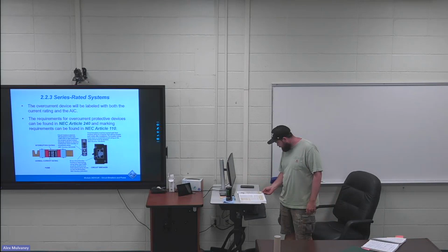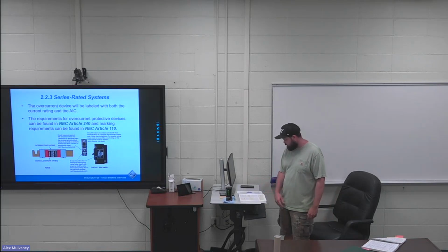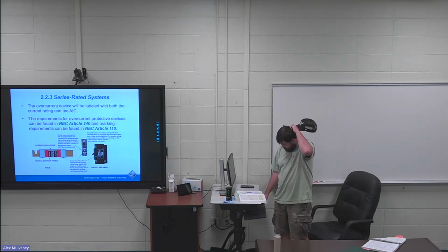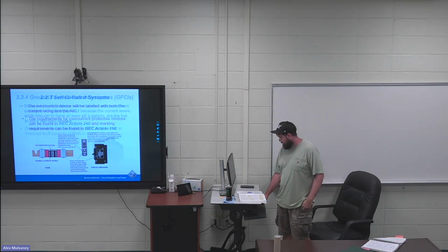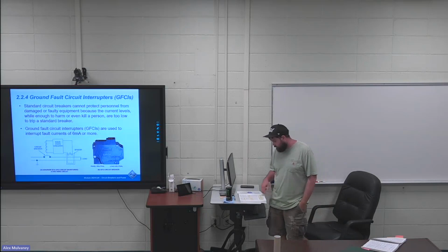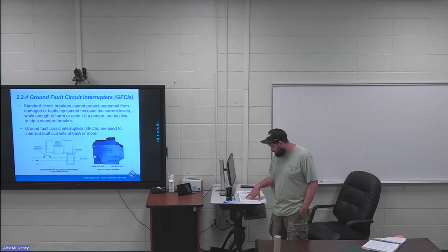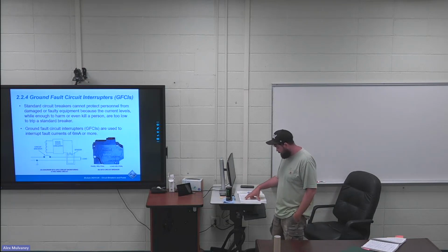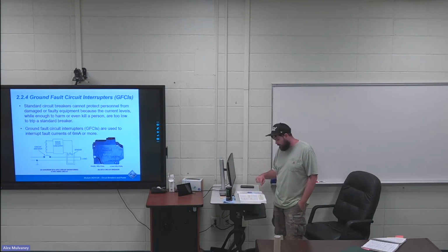They go through bullet points of the effects of electricity on the body, and that last bullet point of the first set of bullet points on page 12 is highlighted. Over 200 milliamps will create severe burns and muscle contractions. The heart is more likely to stop than fibrillate. So that over 200 milliamps, that's bad. Your heart is more likely to stop than fibrillate.